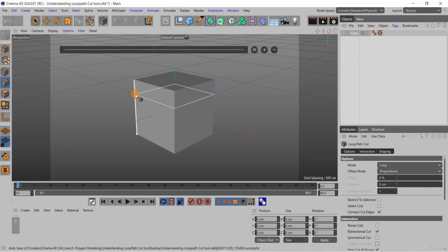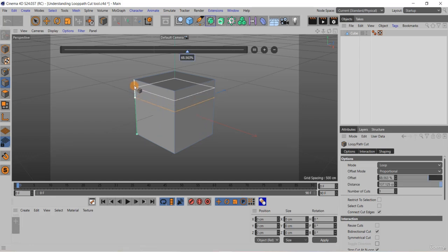Now, as I am moving the cursor on this edge, you can see the loop is also attached to the cursor and you can just click wherever you want this loop to be created, that is the edge loop. And here, one thing you might have noticed is that the edge on which I have clicked is now turned green. And here, one slider is displayed with 3 buttons on it. Also, you can observe that one edit box is there along with this slider, which you can move like this, and by moving this you can see the edge loop which is created is also moving.